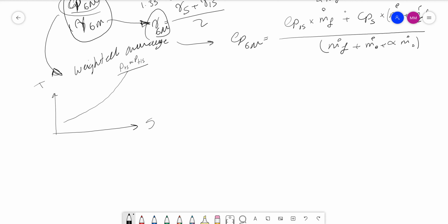Based on our discussion, we know that after the turbine, we have had some expansion, but we still are dealing with hot gas, right? So the temperature is going to be higher than what you would see after the fan. There hasn't been any burning of the gas that is coming out of the fan.